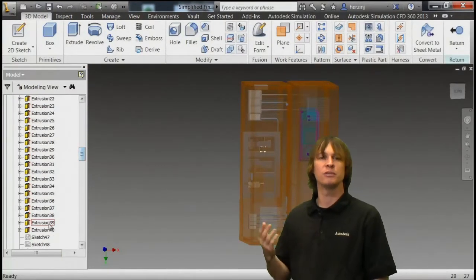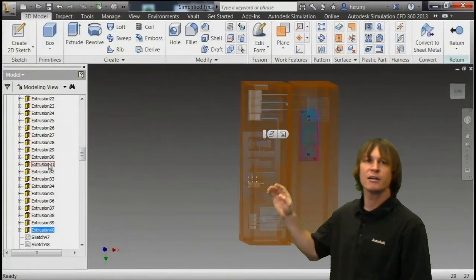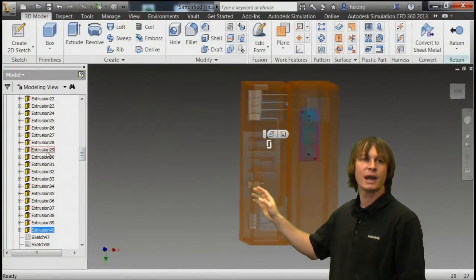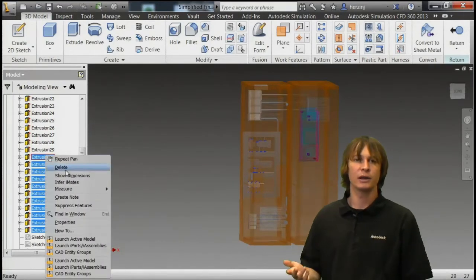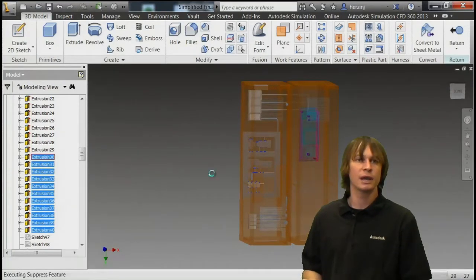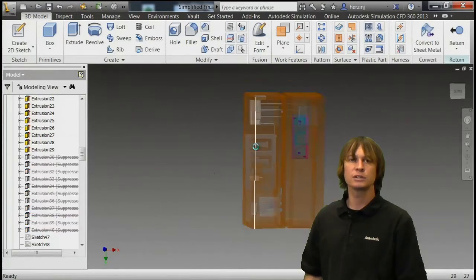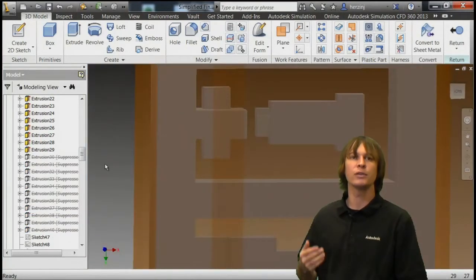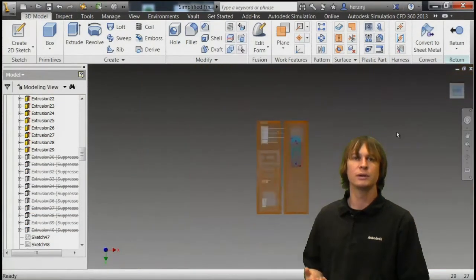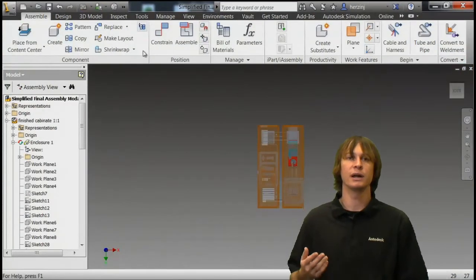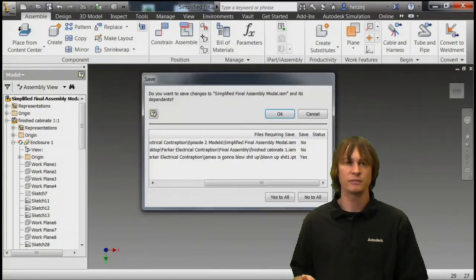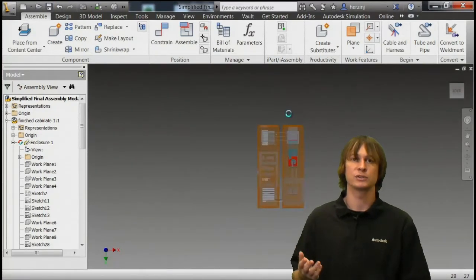And that's to simplify your geometry. We have all these wires that I'm highlighting right now that I'm going to suppress. These are going to just lead to a higher element count when I mesh my model, and they're not really going to affect the results of the model very much. They're very small, they won't weigh much during the vibration. They really aren't necessary for this analysis. Getting rid of unnecessary detail can save you a lot of time and give you better results.